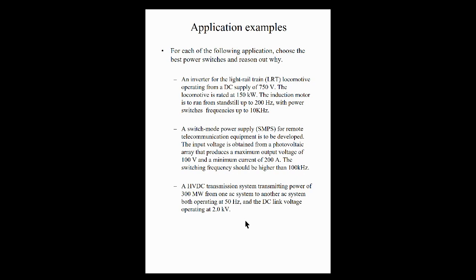So 750 volts. So if you need to understand your current, it'll be based on the power rating. Also, you're told that you want a frequency between 200 hertz and 10 kilohertz, right? So which switch? So that's something that you will consider.